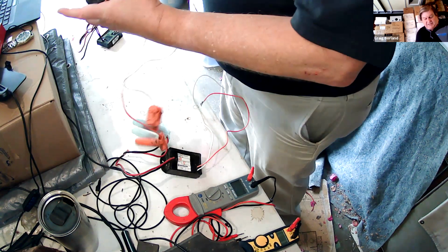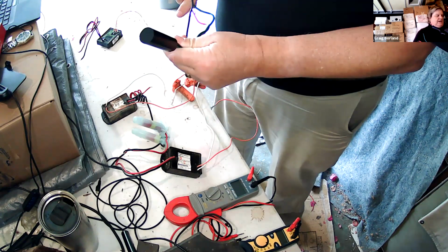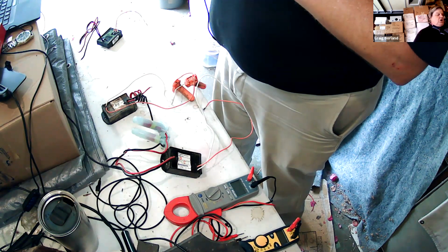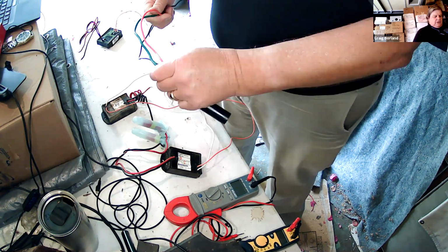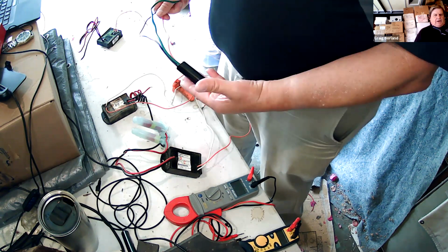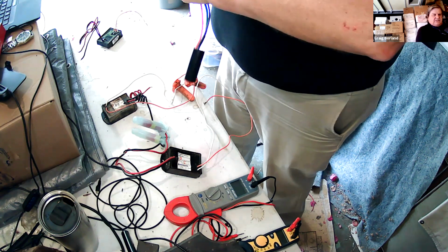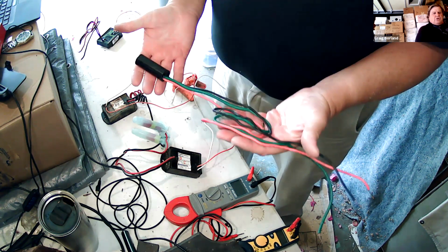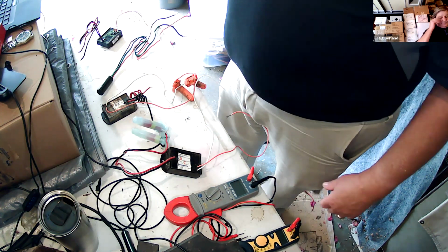There's another decoder that's tangled up. Here is my surge protector. Just a little round tube, maybe 3 inches long, about the diameter of a thumb. It has a green wire for ground, and red and black to match the 2-wire path. It's a surge protector, which you would connect to a ground rod. I need to caution you, because this is where the trouble will come in: these things can short out in the event of a lightning strike or a high power surge. When it shorts out, it creates a short on the 2-wire path. You need to go out and find where the problem is.